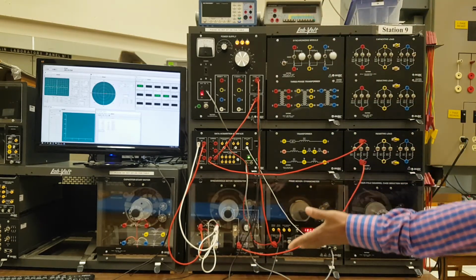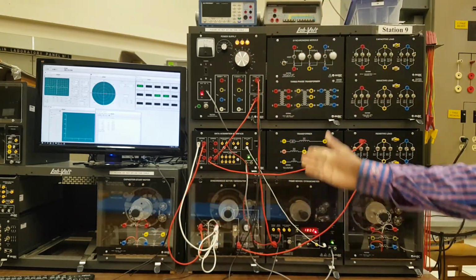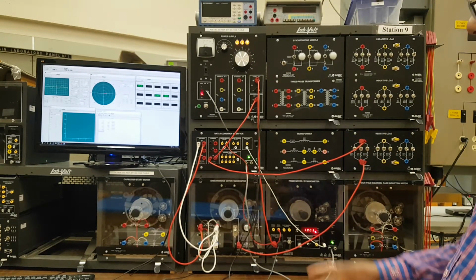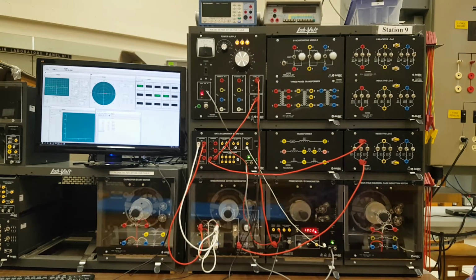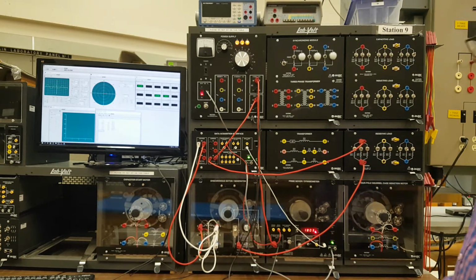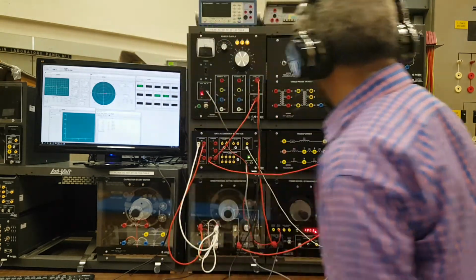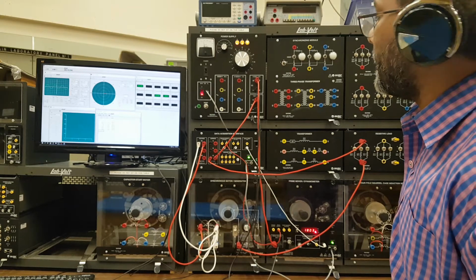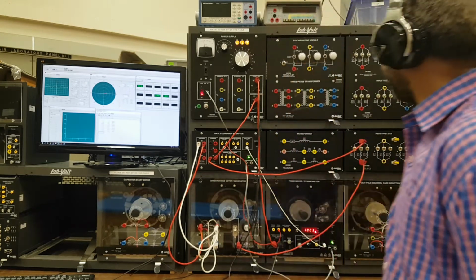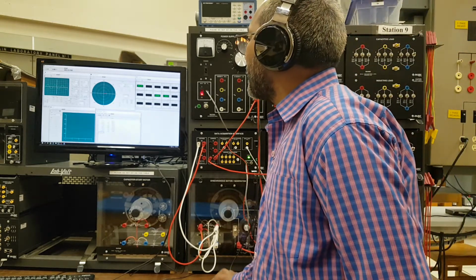So the reason why the speed is not changing is that no power is given. The machine is running open circuit, just inducing and producing the voltage, but no power is transferred to the electrical wire, no load kind of thing. So take the reading. Next one, no change in speed, and I will take the reading there. Next one, no change in speed, and take the reading there.